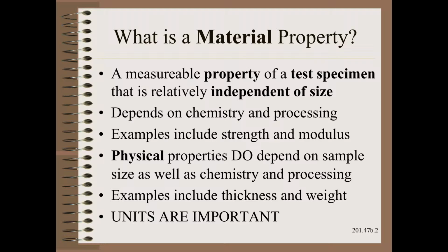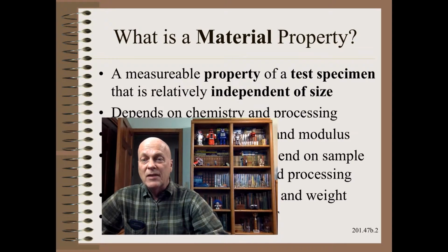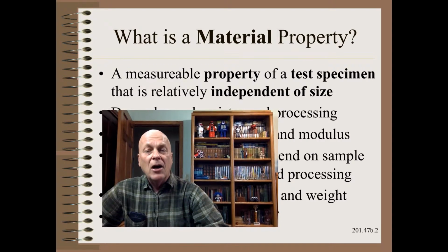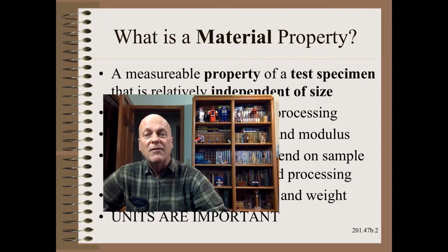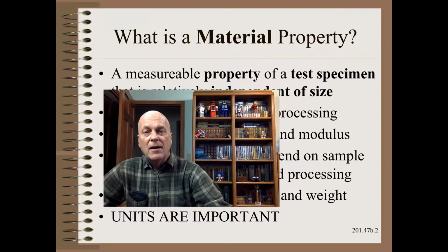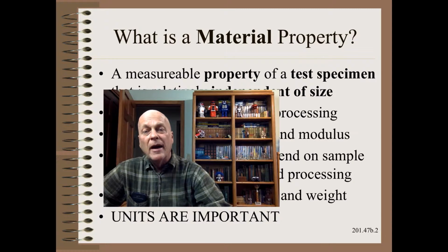There is an area of overlap and confusion that is epidemic in plant test labs. That is, what are the units for the value or the numbers given by the test instruments? Some units are peculiar to a specific test and will not be discussed here. However, many are a blend of material and physical properties. Let us give the common example of strength. The most common units reported would be pounds force in the U.S. system and perhaps grams or newtons in the metric system. Presumed by standard is the specimen width and the thickness of the sample being tested.